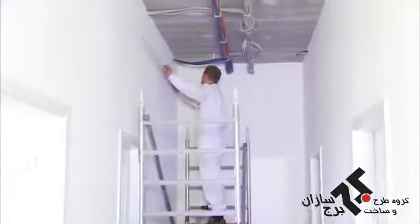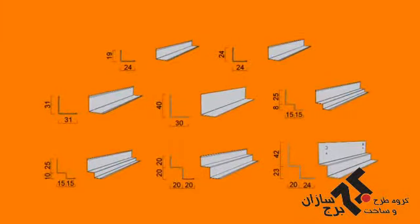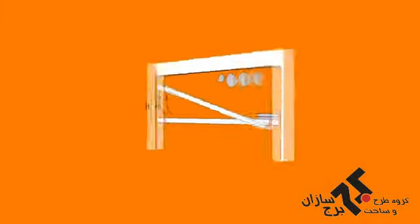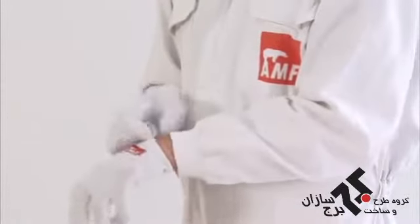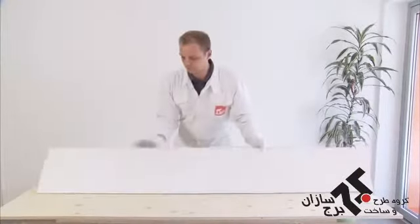The perimeter trim is fixed at the required ceiling height. Different perimeter trims can be selected depending on tile type, weight and format. This in turn determines the minimum installation height. As a rule, corners are usually mitered. Next up are the first ceiling elements, usually starting with a cut tile depending on the corridor's dimensions and room layout.